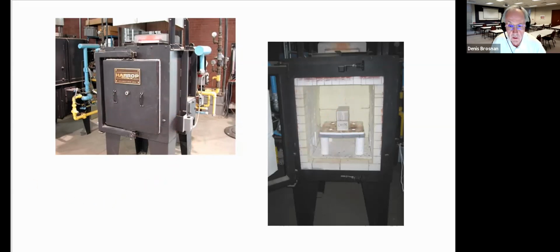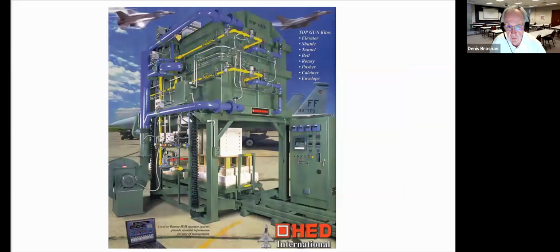It's just what we needed. Here's a batch kiln. This is an elevator kiln. These kilns are particularly used for high temperature products. I had to copy this one off the internet. I have an elevator kiln in my laboratory, which is an electric kiln fired with moly disilicide heating elements. It's much smaller than this particular kiln, but nevertheless, I didn't have a picture available of that kiln.